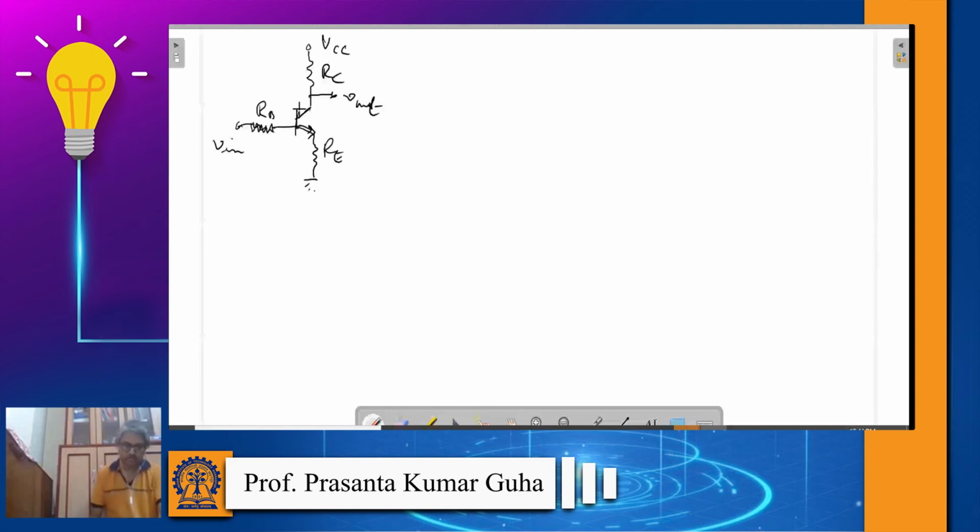The reason the gain will drop is simply because a part of Vin will be dropped across this resistance RB, okay. So Vin will drop across RB, will drop across VB, and also will drop across RE, that is basically effectively beta plus 1 RE, right? You remember? So Vin will basically drop now with this additional resistor RB.